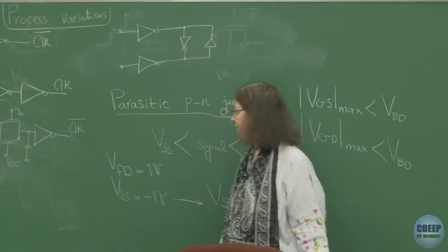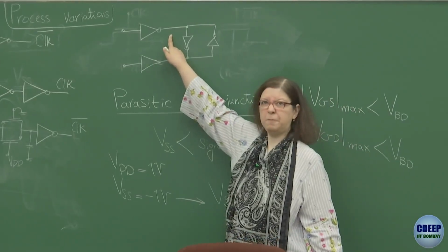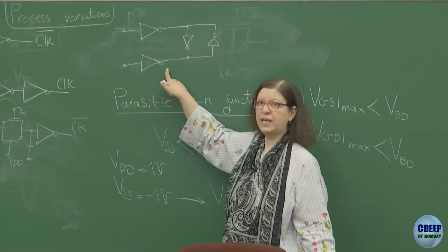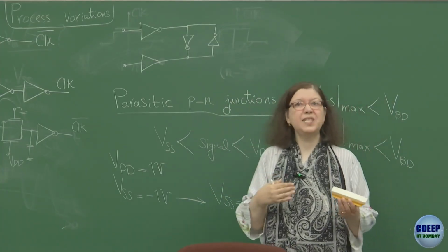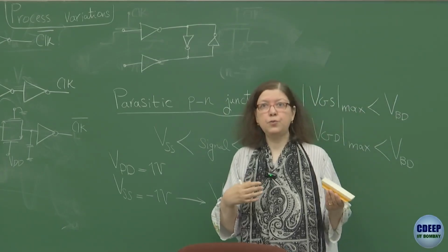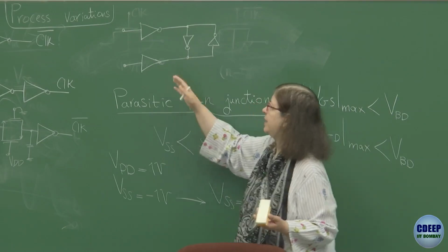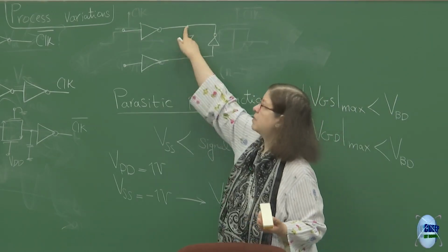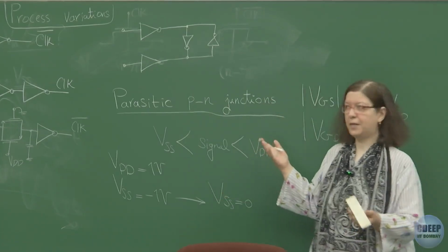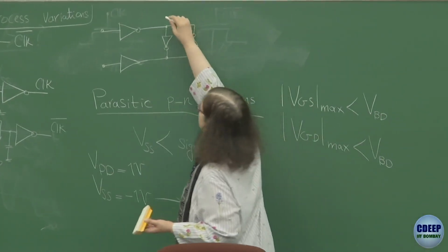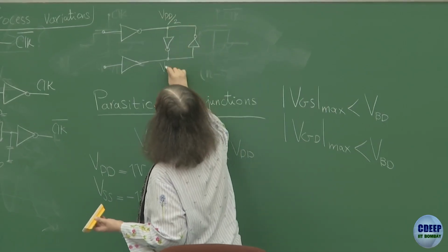But here, eventually what you are doing is that if one of them is strong and one of them is weak, anyway they are coupled to each other. So therefore, always one of them doesn't allow the other one to move. They have to move together. See, they have to work together. Otherwise, this node and this node will be stuck at VDD/2. The only condition this can work where everything is analog and fixed is VDD/2 everywhere.